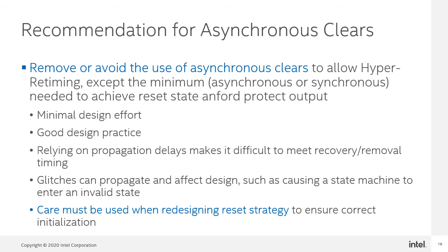If it does, then in relation to all of the potential Hyperflex modifications, this is considered to be a minimal design effort fix. Many FPGA designers have already started to move away from using asynchronous clears. With the clock speeds of today's larger FPGAs, it has become increasingly more difficult to meet recovery times when using the global clock trees to distribute asynchronous clears than in the past.